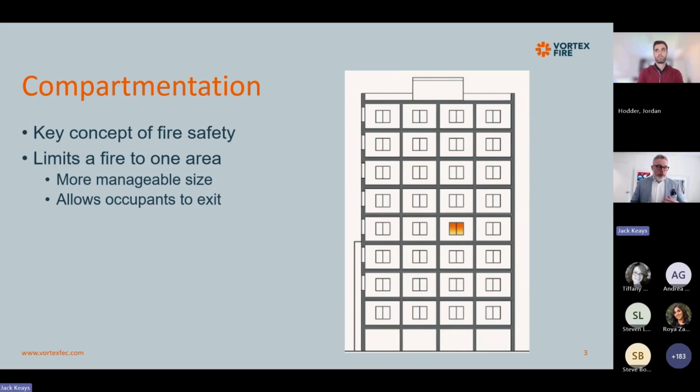The benefit is that when the fire department turns up, and when people are egressing, the whole floor, the whole building isn't on fire. You're just dealing with a small portion of the building. It limits the area and allows occupants to egress, and also keeps it to a more manageable size for firefighting. You'll see this in sprinklered and unsprinklered buildings, and it's a key concept of the building code. So anytime we go through a fire separation with a fire resistance rating, we have to make sure those openings are protected, or if they potentially are exempt, depending on how they are arranged.